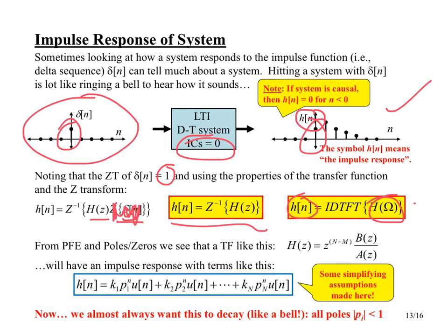And then finally, if we think about our system transfer function that looks like this, if we make a few simplifying assumptions to get an easy scenario to think about, and we do an inverse transform of this, something in this form, maybe not exactly in that form because of these assumptions, but pretty close, we can find that we get a sum of a bunch of exponential terms, and each one of those p sub i's is one of the poles.